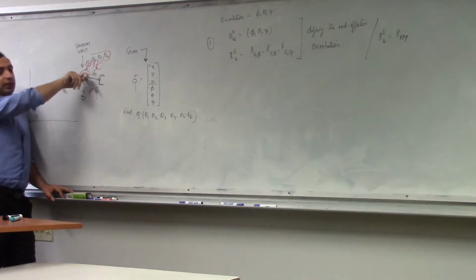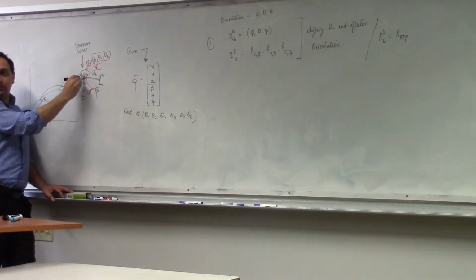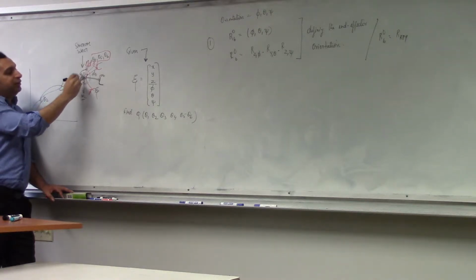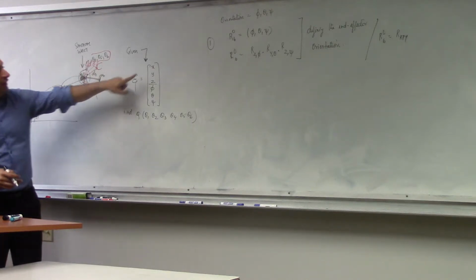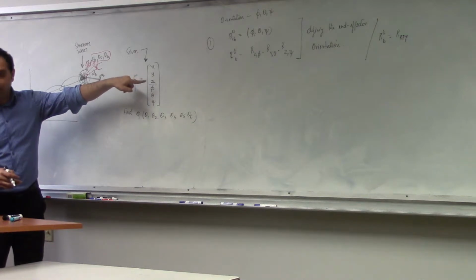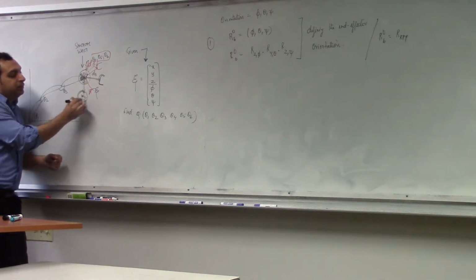The end effector orientation will change. This point remains constant, right? Because at this point you have 3 joints concentrated at the wrist center. So it only affects the orientation. It will affect XYZ of the end effector. But the problem is, it will not change WC.